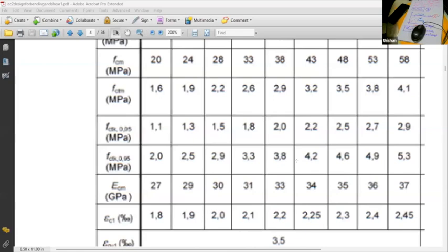if the building is stiffer, it will have a lesser wind-induced acceleration, and you'll find now, people are happier because your calculation was more based on 1 year return period. Now suddenly you find now you are even satisfying the 5-year return period on the wind-induced acceleration limits. And you'll find you have a much superior product. And that product improvement has come from the concrete technology that you use, not by the design. Is that clear? Yes, sir.